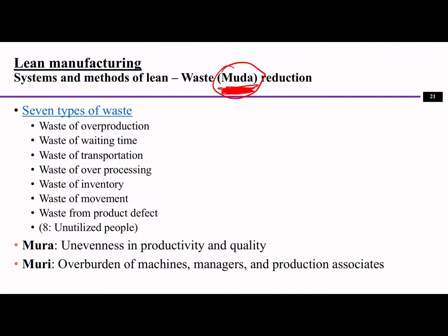Say you're operating a machine and you put the machine really far from where you put the materials. In this case, the operator has to move a lot, and that's going to cause some issues. And waste from product defect, because defect is non-value added, and in fact it decreases the value. So get rid of or reduce defects by identifying where these wastes are.